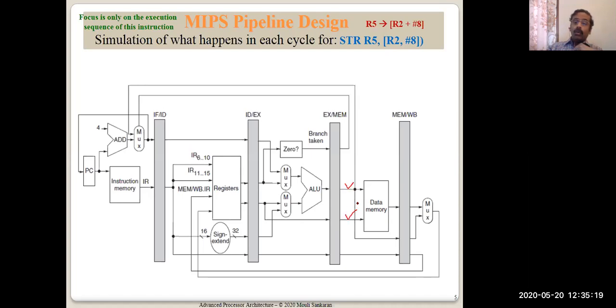Okay, you may wonder, how do I know this is an address and this is a data? That's a good question. You may think this is address and this is data, but you have to have some common sense and logic, saying that address is coming from ALU because it is performing an addition of base address and the index, finding the effective address EA, which is coming from ALU, which is shown like this. So address must be coming here, and data should be coming here.